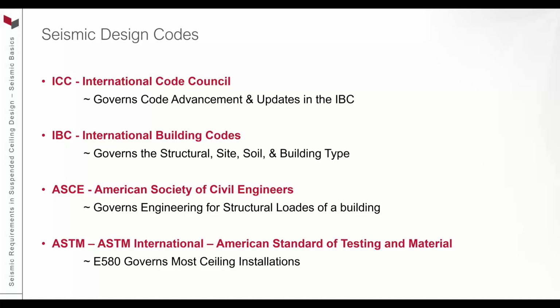And it's not just seismic loads, it's wind loads, it's snow loads, it's rain loads, it's all kinds of different loads, but the seismic loads are built within the ASCE, and so it helps govern how buildings are built within the IBC. And then part of that, where it comes down to ceilings, we get involved with the ASTM. And so the ASTM actually is under the ASCE in the sense that the ASCE has transferred the responsibility for ceilings to the ASTM.